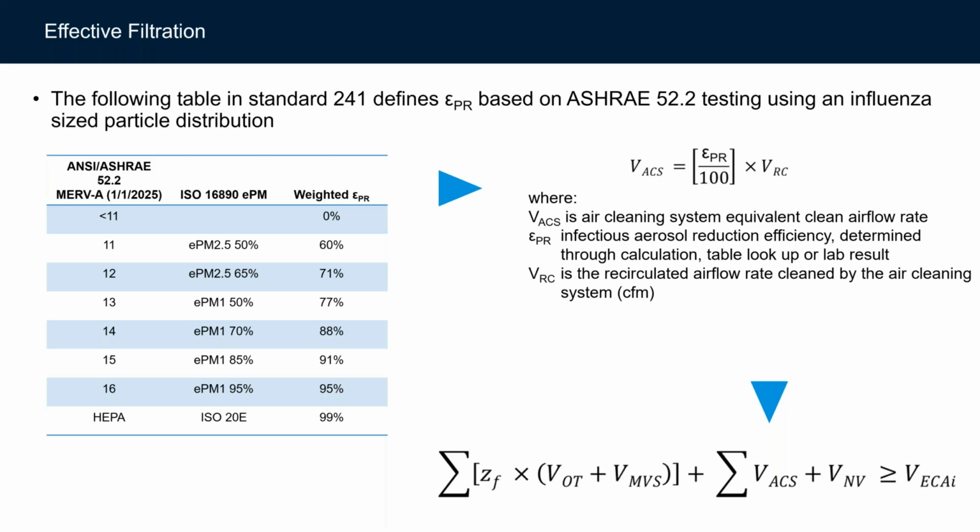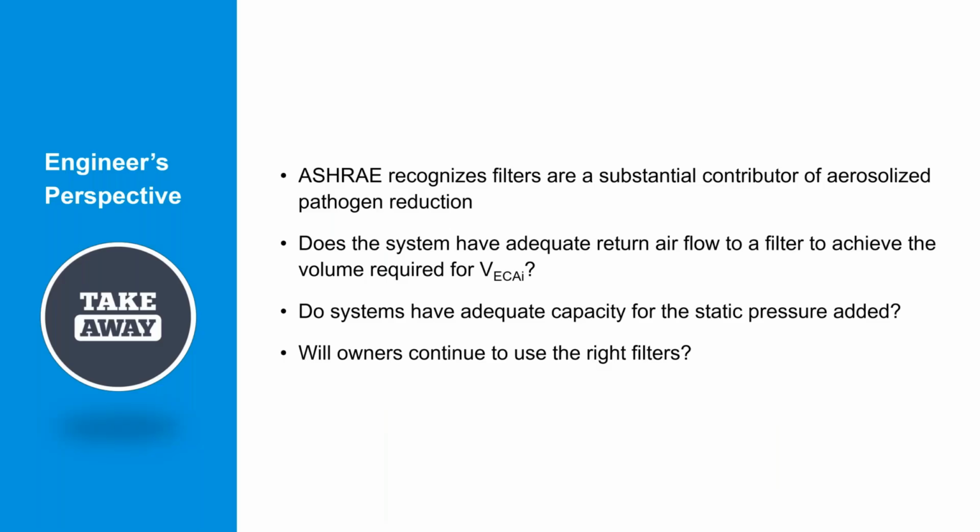And so you add that to the outdoor air, and that might get you to the full ECA. Oftentimes what I've seen is it gets you relatively close with a MERV 11, and then you want to add something else like an electronic air cleaner to cover that gap. And the reason why ASHRAE is doing this is they really do understand now that what's happening in the space, a layered approach with good outdoor air, good filtration, and something else that's safe and effective will completely provide a way better scenario for cleaning that space and providing safe air cleaning.